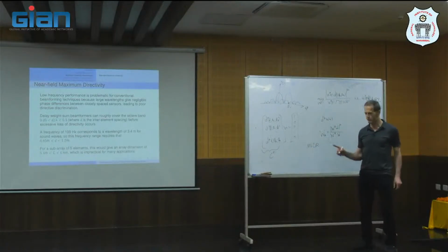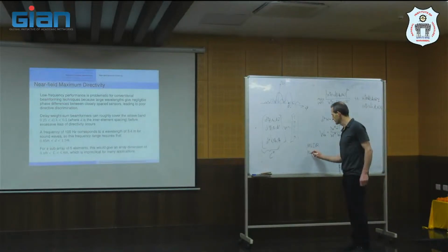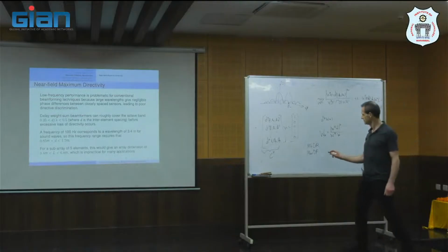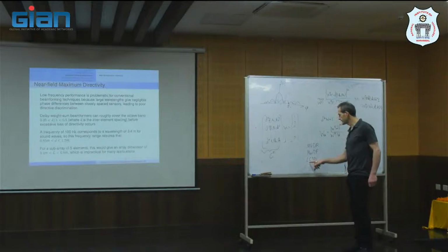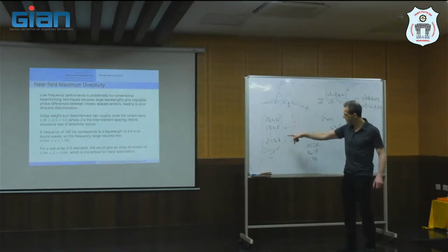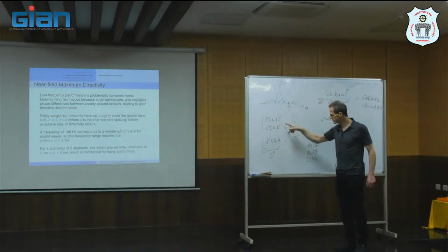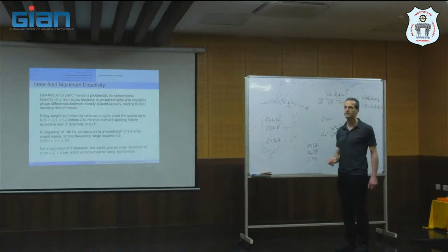We saw maximum directivity factor, the max directivity factor beamformer. We saw LCMV, linearly constrained minimum variance with the matrix C. So if we have more than one constraint and one direction, if we have additional linear constraints using this matrix of constraints, we call it linearly constrained minimum variance beamformer.